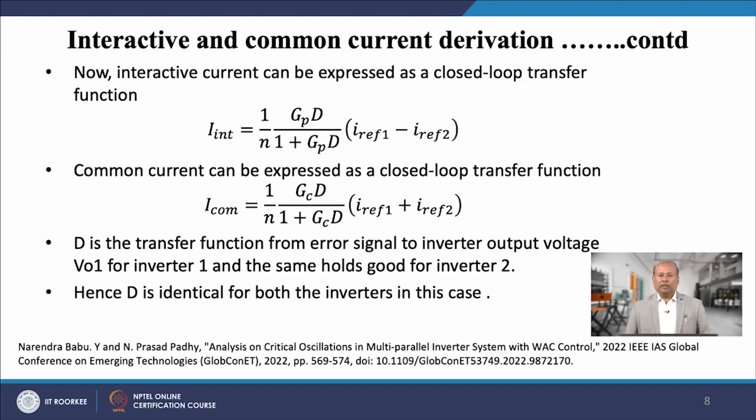What does this mean? It means that if we change the reference current of any inverter, apart from the dynamics in the common current of this inverter, there will be dynamics present in the common current of the other inverter also, which die out with time.